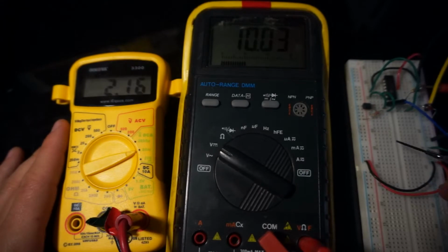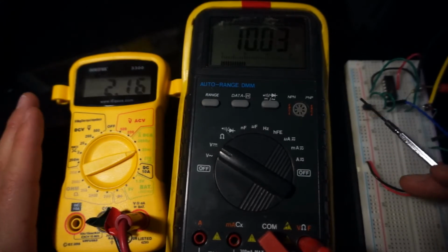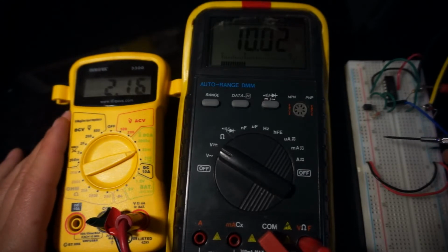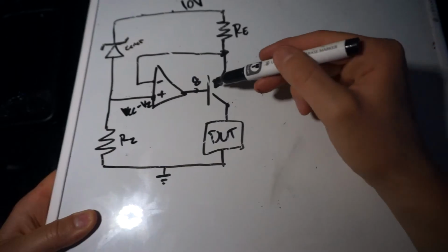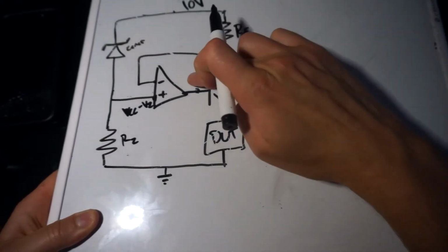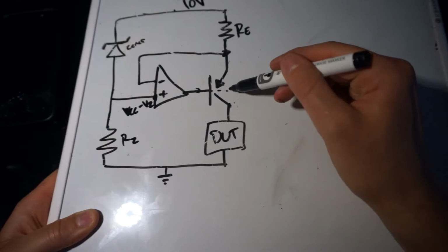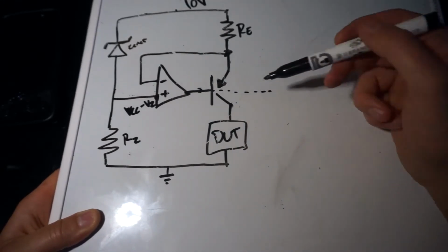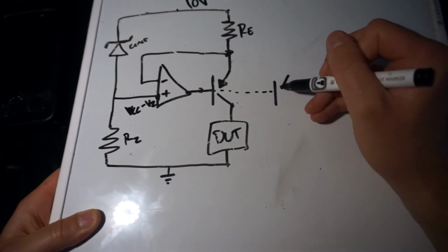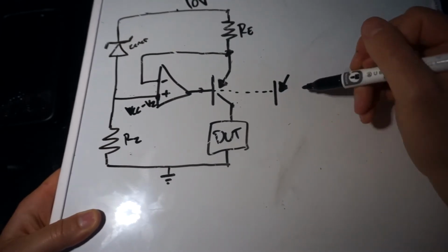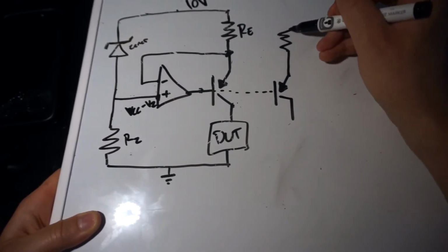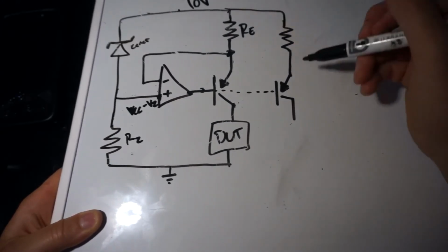One thing it does make easy is that this op amp has now locked down the base voltage of the PNP transistor. So what we can very easily do is make a current mirror. For a current mirror, all we're going to do is also connect this output to another, hopefully identical, but of course not always exactly identical, transistor with its own emitter resistor, just like this.